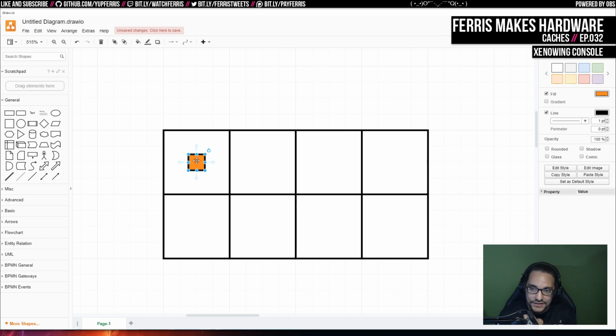As this moves around, if I were to sample this and then the next texels, it would just be this plus one. But as we move around, this plus one might change. So I organize this texture memory to be in 4 different banks, which is what I do so I can read 4 in one cycle.